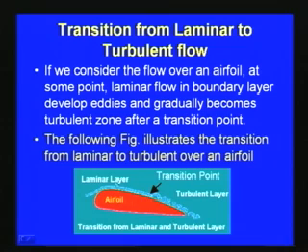As you can see here, the free stream velocity is coming here, and this is the airfoil, and the boundary layer formation takes place. This is the laminar layer, and after some time a disturbance starts, and we can identify this as the transition point. As we have discussed in earlier lectures how turbulence is created, the boundary layer now transforms to turbulent like this.